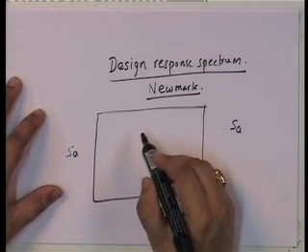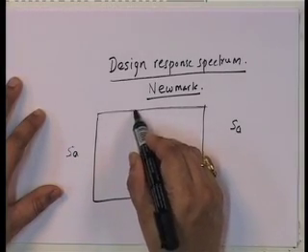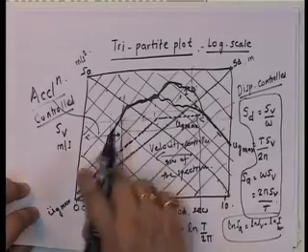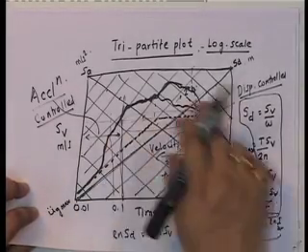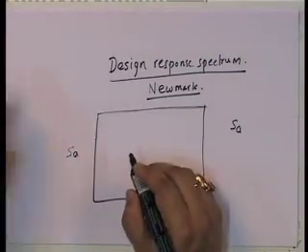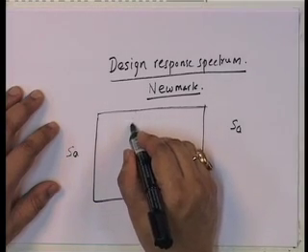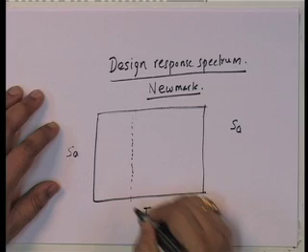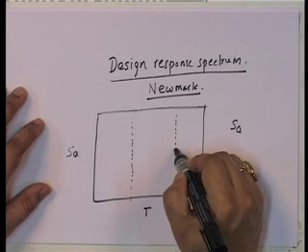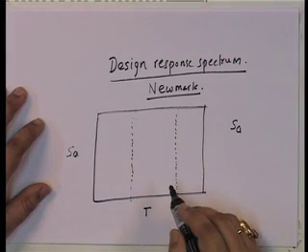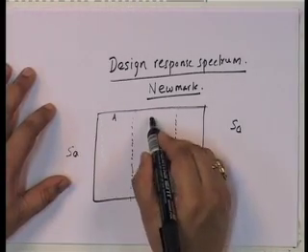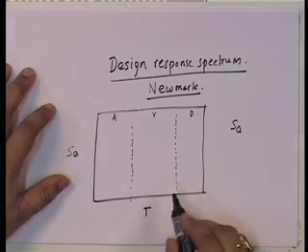He said that look, I am going to break up, and this is based on what we discussed over here, and from these tripartite plots for a variety of ground motions, and plotting them, they discovered that look, there is a situation where I have an acceleration controlled region. Okay. So, this is acceleration, this is velocity controlled, this is displacement controlled.